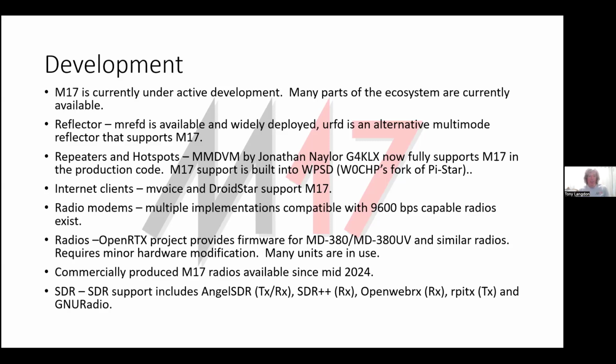For repeaters and hotspots, Jonathan Naylor's MMDVM is pretty much the workhorse here, with full M17 support in production if you load the latest firmware. And on the software side, WPSD, which started life as a fork of Pi-Star, officially supports it and is the officially recommended software for using with your MMDVM.